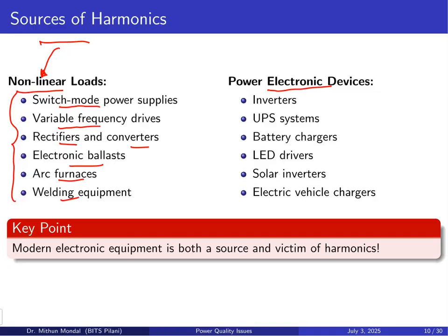If your load is non-linear, the current will also be impacted, because if the load is linear, the current will increase linearly with respect to voltage. If the load is non-linear, then the current will be impacted and harmonics will be present.